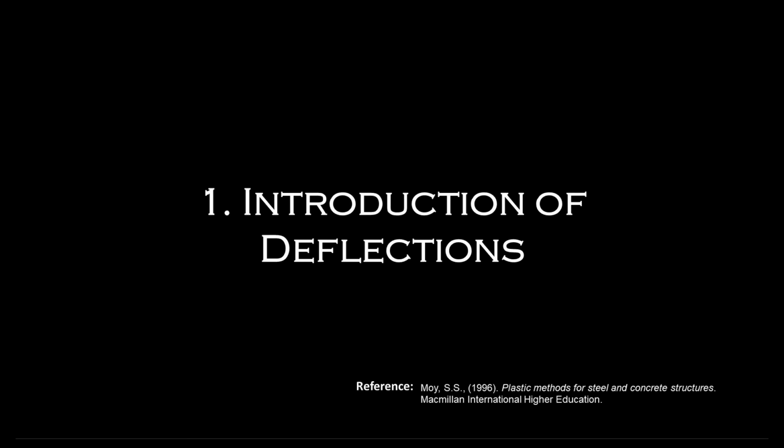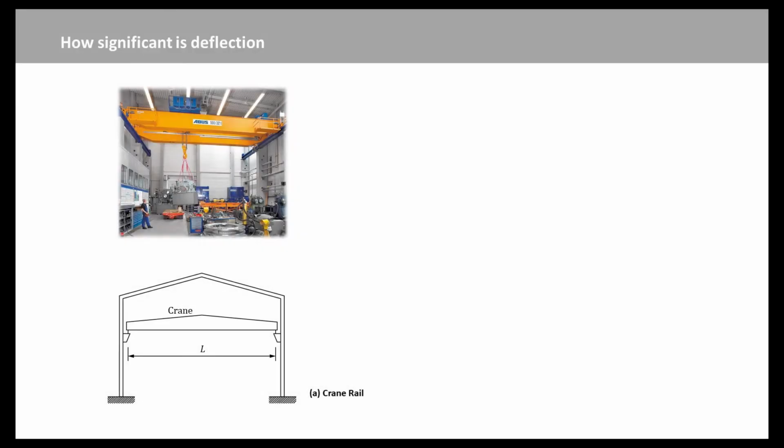In the virtual work method, the collapse load was found by considering small virtual deformations of the collapse mechanism. However, the shape of the structure before deformation of the mechanism was assumed to be the same as when there was no load on the structure. In other words, all deformation before collapse was ignored. There must be deformation before collapse. But how significant is it?